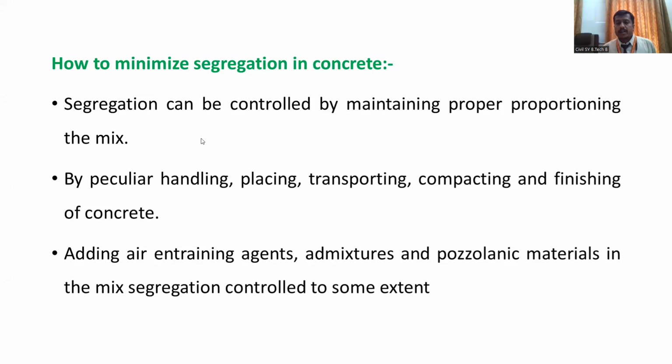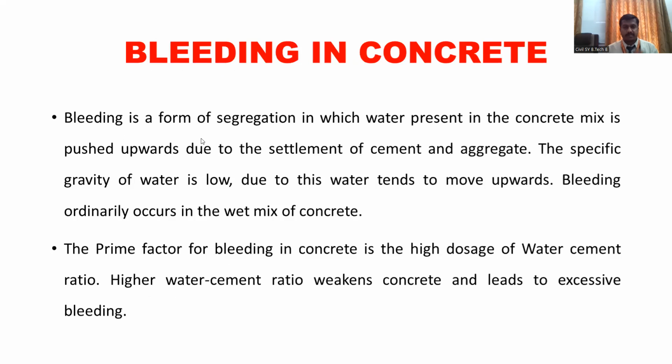Secondly, by proper handling of the concrete, proper placing, proper transporting of the concrete, and proper finishing of the concrete, you can achieve minimization of segregation. Then by adding some air entraining agents or admixtures or pozzolanic materials in the mix, again you can control the segregation. Okay, these are some of the things which are used.